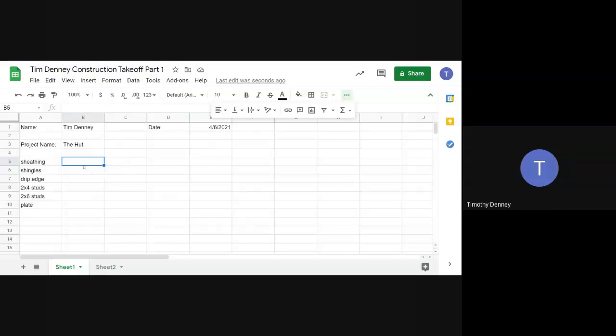And if something is 4 feet by 8 feet, and it's a rectangle, to find the area of a rectangle, we just multiply the length times the width, so we multiply 4 times 8. Now, you don't have to put this on here, I'm just showing you, but a 4 by 8 sheet equals 32 square feet. Each sheet can cover 32 square feet.